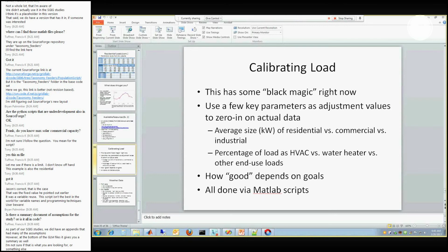It's really going in and looking at a comparison of these two load shapes and trying to understand what the differences might be. So, for example, if I have feeder data that looks like an afternoon peaking unit, and mine is showing something more like a morning peaking unit, what I may go back and do is record out the different end-use components to try to understand who's peaking in the morning and causing that peak, and then try to modify the load shape behavior so that it's more representative of the feeder I'm looking at.